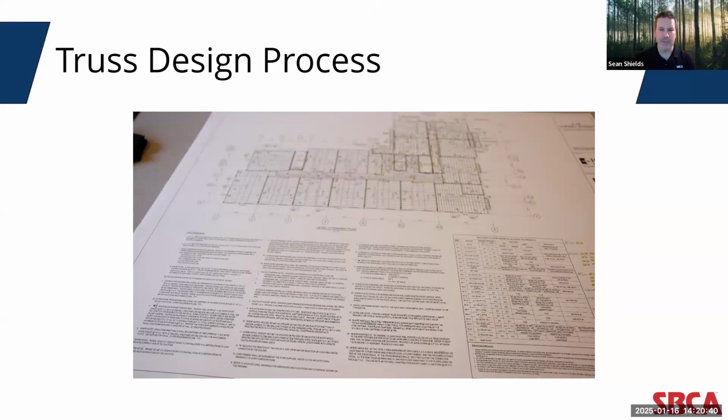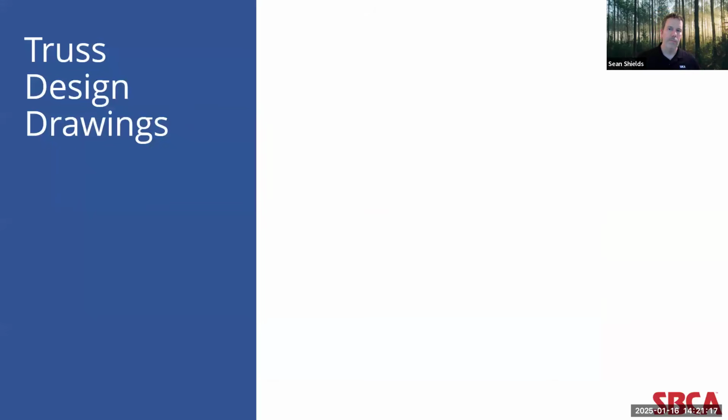The reason why I bring this up is because truss placement diagrams are often talked about in the same sentence as truss design drawings. They're both aspects of the truss submittal package. But I want to make the point that the truss placement diagram is not an engineered document. It is merely a graphical representation of the information contained in the individual truss design drawings. So while truss design drawings can be and regularly are reviewed and sealed by a registered design professional, that is not the intention of a truss placement diagram.